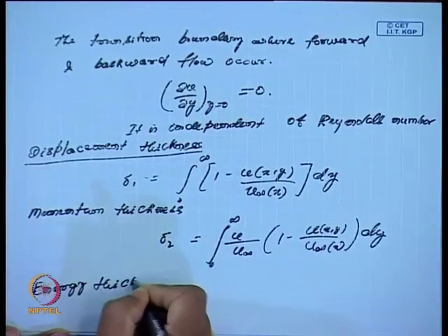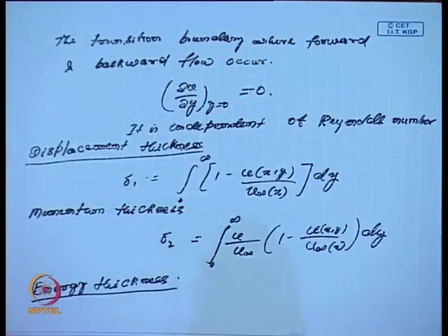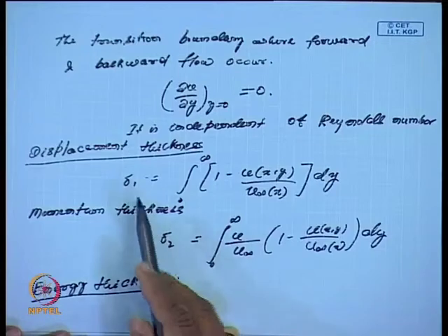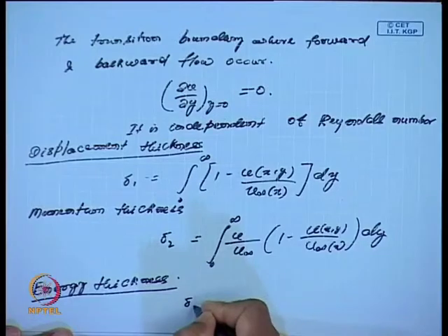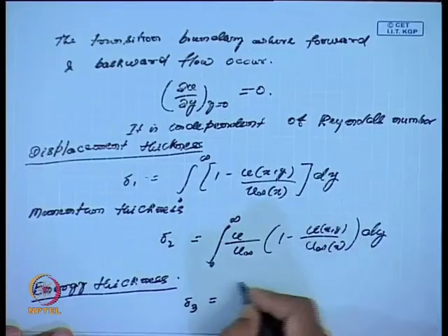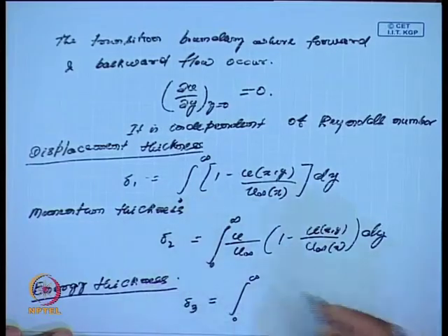In fact, there are a class of problems where, instead of going for direct u, many times we are interested in the calculation of this displacement thickness, momentum thickness, and energy thickness. That helps us in obtaining various physical quantities of interest, which will be obvious when we work out one problem on this. And this we will call, integral 0 to infinity, the energy thickness.